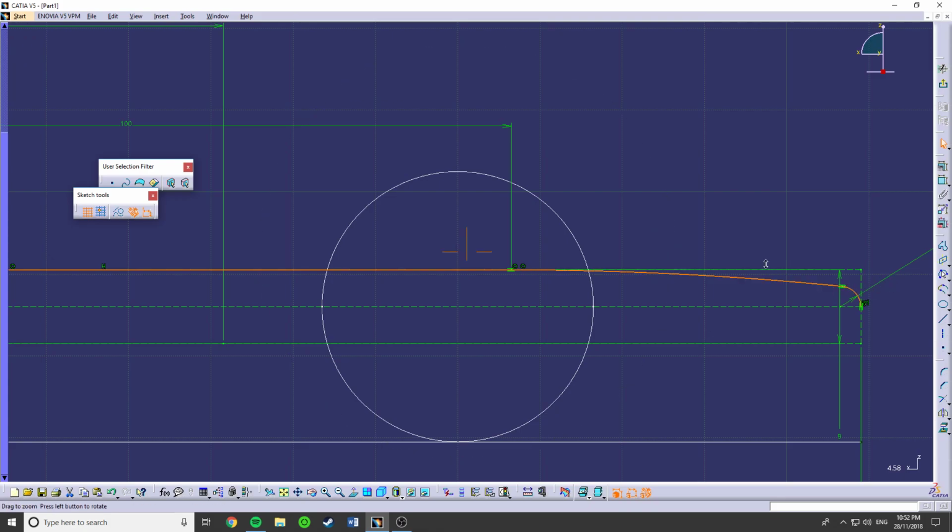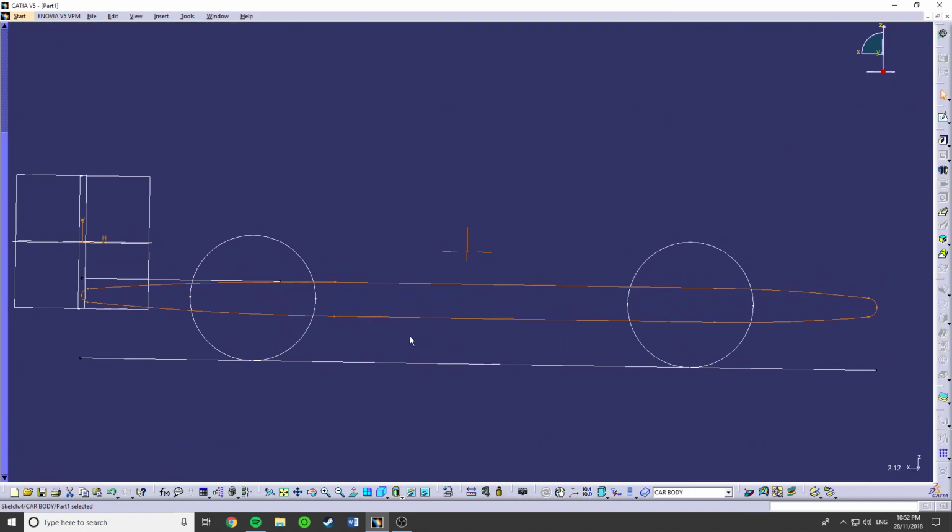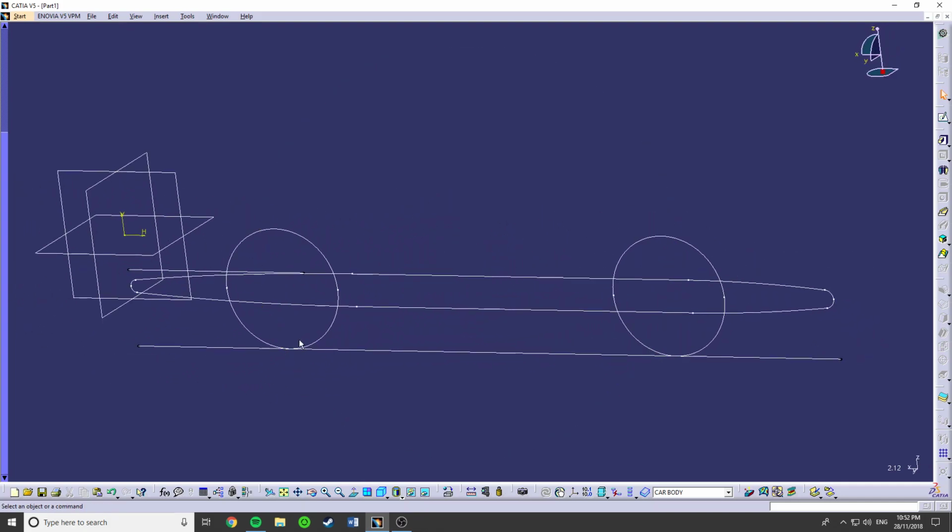So now we have all of them selected. We're going to use the mirror tool again, and we're going to mirror it over this. So here we go, and if we leave this sketch now, it's going to look something like this. Now you see this black dot, this black style dot up here and up here. If there's any of those in our sketch, we know that it's still open geometry, but it seems like it's pretty good at the moment for this.